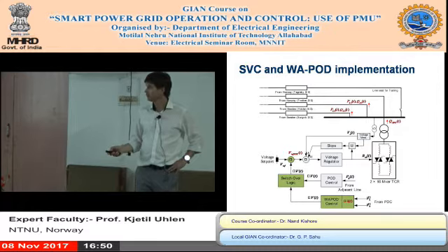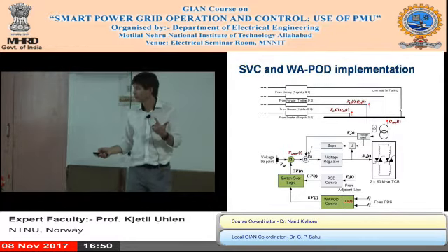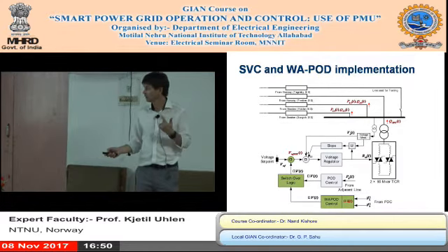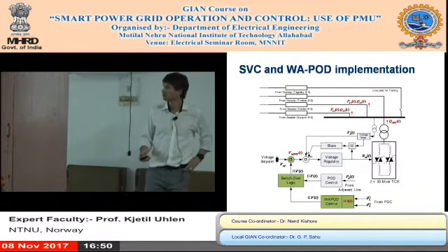And then we needed some switchover logic that worked in the sense that if the latency of the signal was discovered to be too long or the communication was lost, then we would switch over to the local. So there was no risk involved in that, and it's a solution that works.